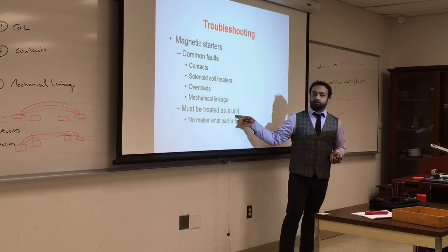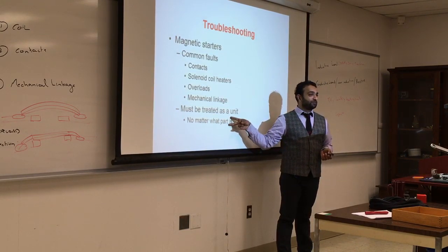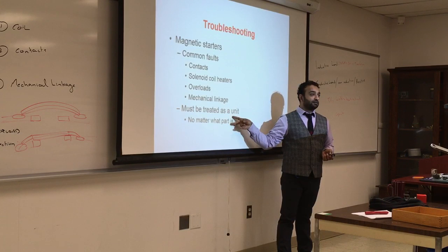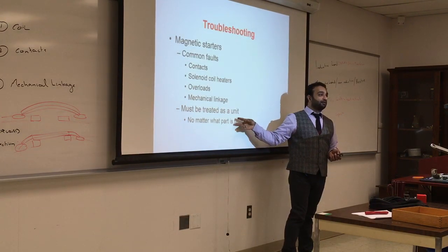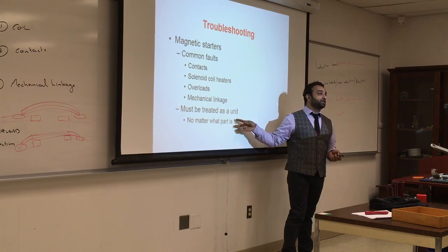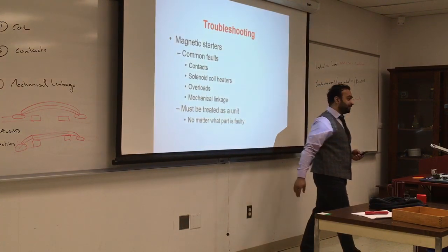Must be treated as a unit. What does that mean? One piece fails, the whole thing's failed. Exactly. Did you guys pay attention to that? If one piece fails of the magnetic starter, you change the whole thing. We do not repair it.